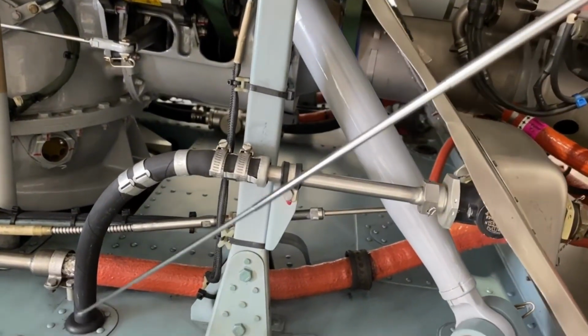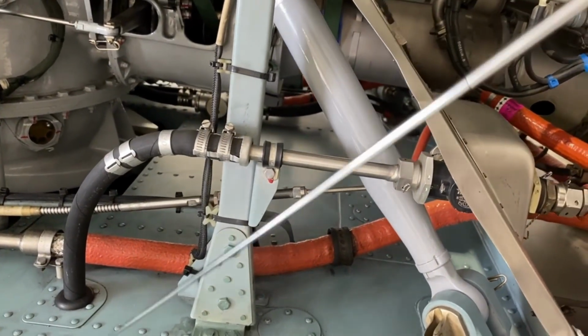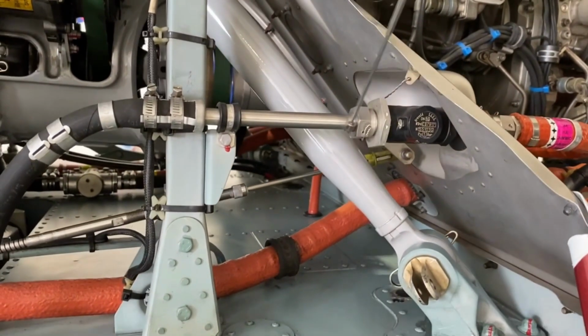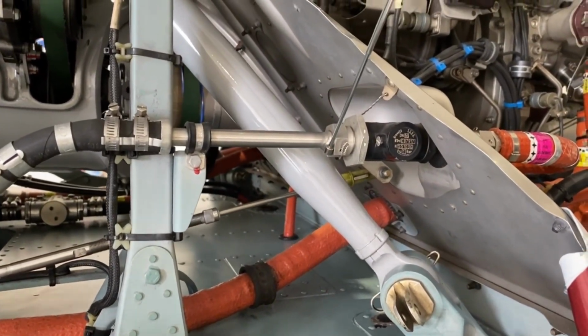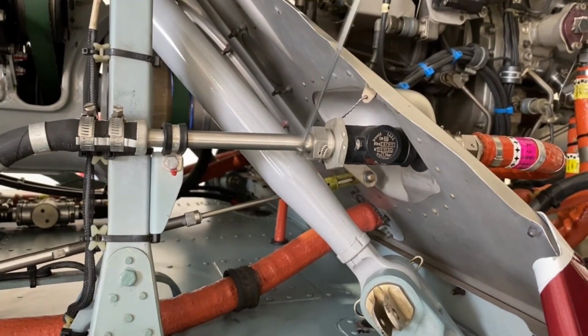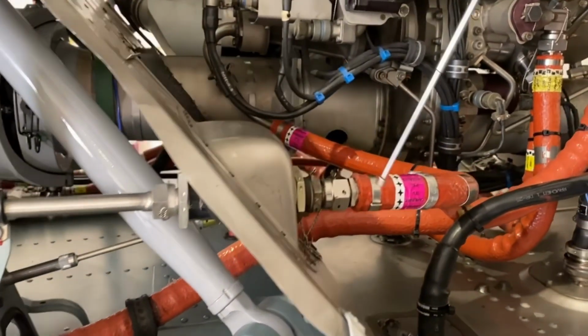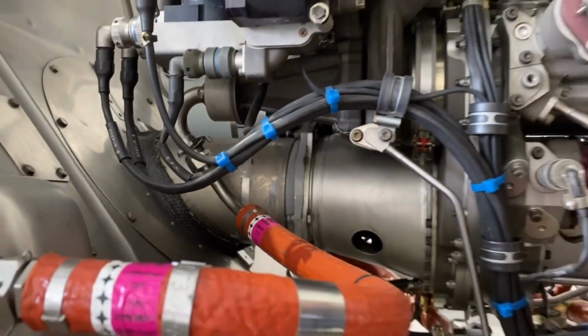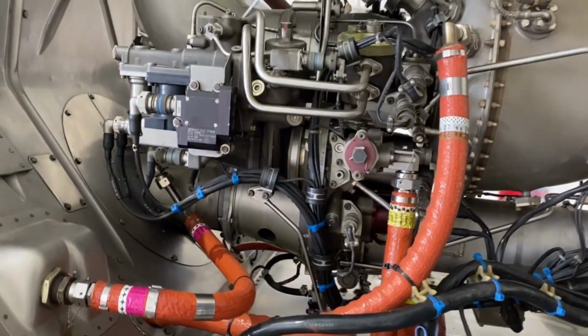Guys, here is the fuel inlet that comes from the tank, which is down here at the bottom, right? It comes here, passes through the shutoff, and is controlled by a lever in the cockpit by the pilot. It's only closed in case of fire. And this fuel comes in here from below into the low pressure pump, which is part of the HMU. When it goes into this low pressure pump, the fuel comes through this pipe.